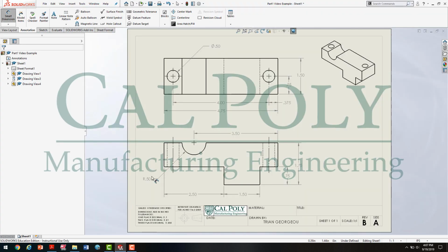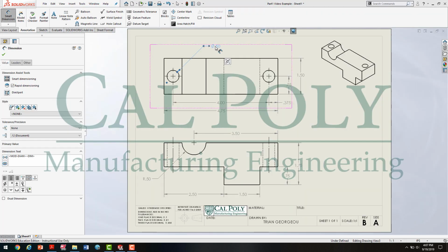So moving back to SolidWorks, I can click on the dimension, and down here by the dimension text, you'll see it says mod DIAM. That's going to be the diameter symbol it places in there, and the carets are the dimension it pulls from the solid model. So if I wanted to go ahead and put 2 by in front of the diameter symbol, I click my mouse button on the dimension text and I type 2 uppercase X space.